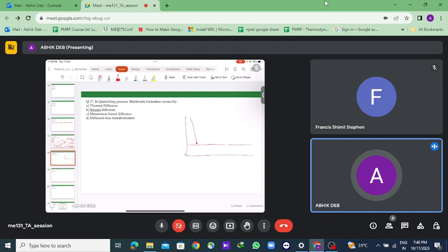Okay, and this is the time where the transformation will take place. There will be cooling till this point, then homogenization at a constant temperature, then another cooling which will result in the formation of martensite at this temperature. This point must be less than the martensitic finish temperature, and then we keep it again constant. Okay, so this is like a stepped formation of martensite.